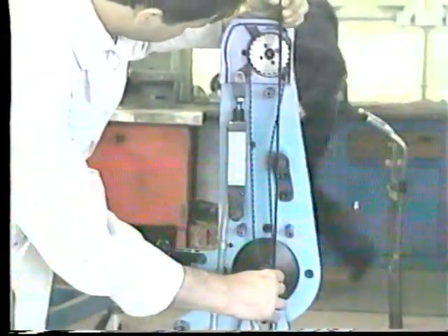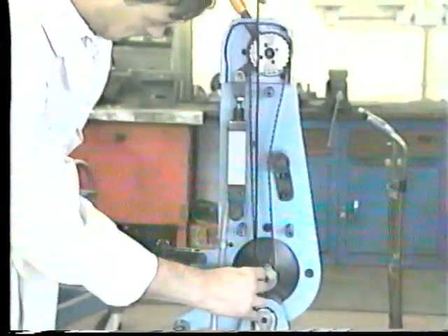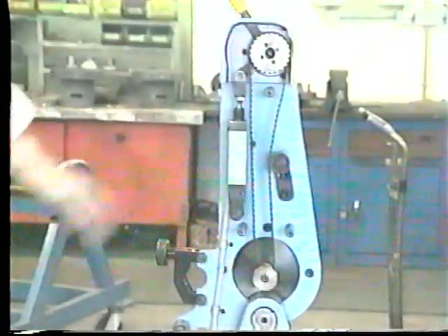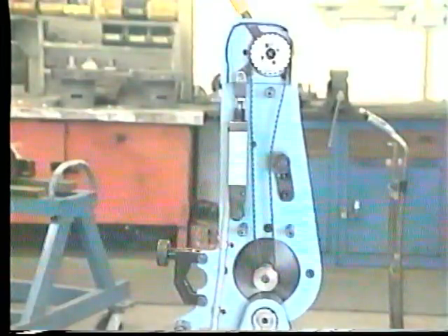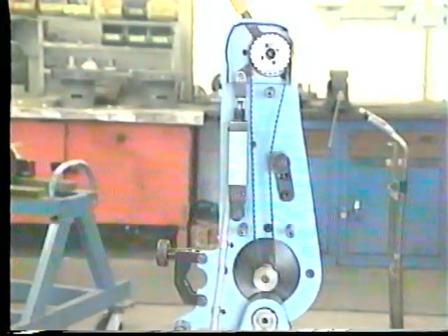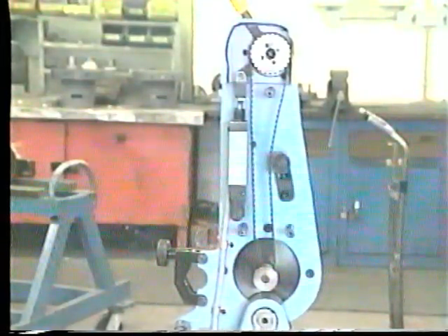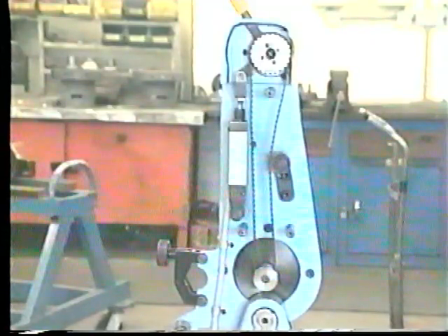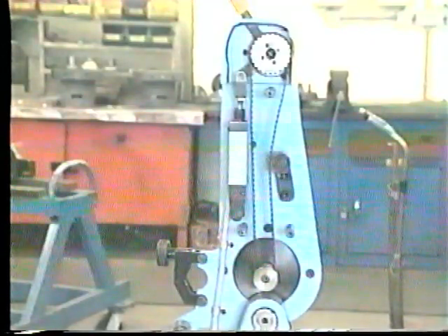Misalignment is also a cause of failure, and care should be exercised during installation to make sure that sprockets are aligned as carefully as possible. Just as with friction belts and pulleys, use a clean white string or a straight edge. Accurate alignment will make timing belts, sprockets, and bearings last longer.